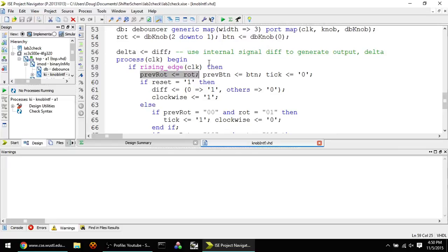Well, consider the way that the process works. It is sequential; it does operate things sequentially, but the values don't update until the very end. The actual values themselves do not update until the very end. There's one exception to that. Anybody know what the exception is? It updates right away. What kinds of values are these? If I had to call them something, I'd say I created a bunch of blank to help me out with this process. Signals. These are signals. Do we have something else we can use?